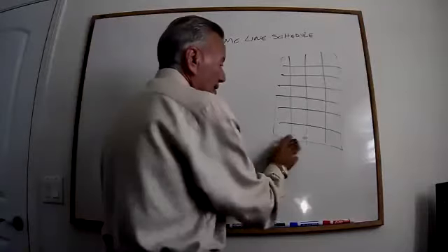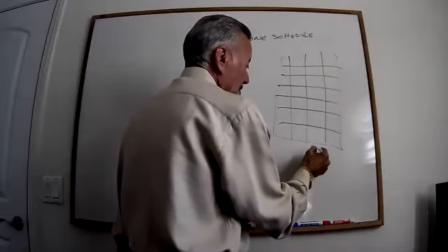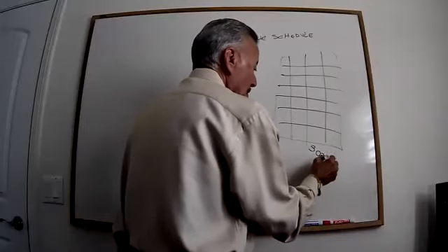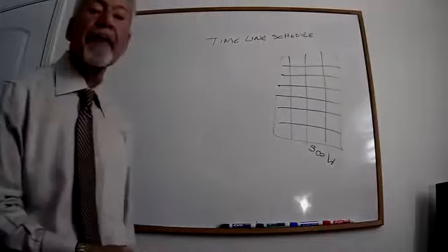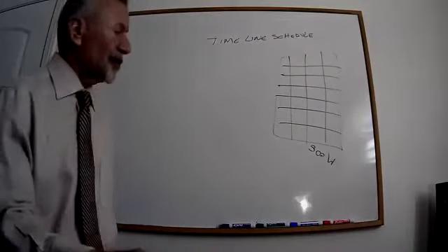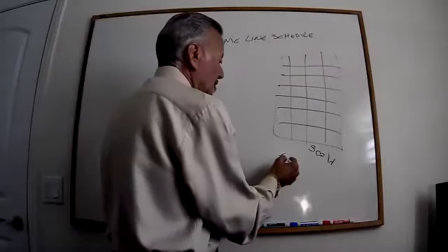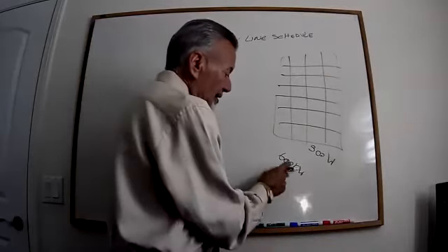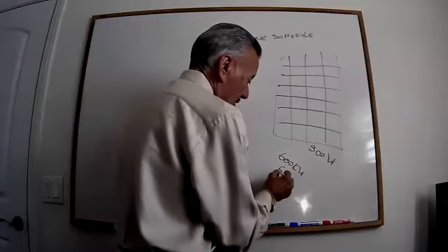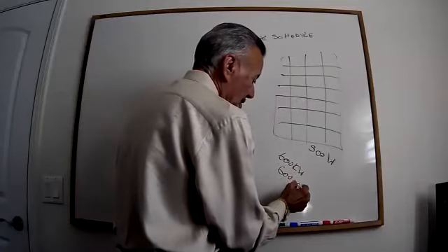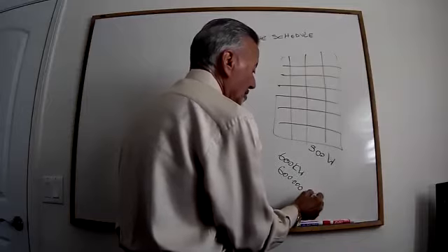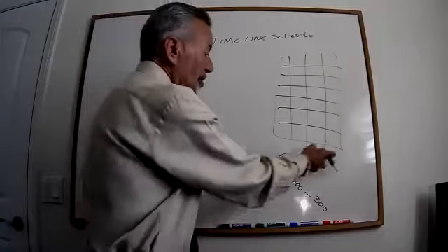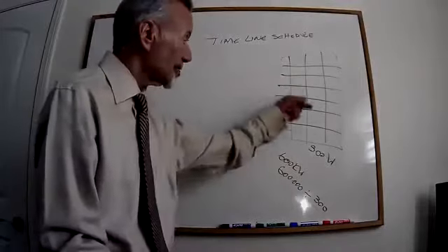And this will generate, let's say, 300 watt of power, one panel. Now, if you decide to do 600 kilowatt, that means you get 600,000, you divide it by 300, and you need 2,000 panels, 2,000 panels like this.